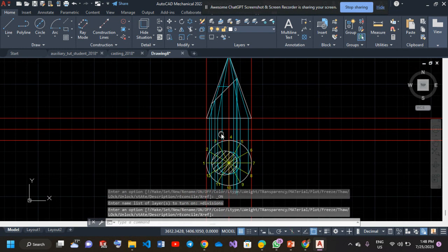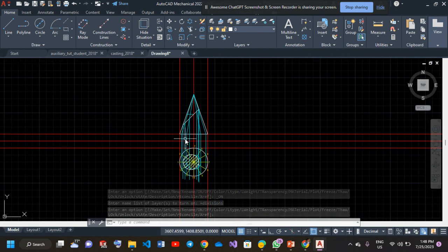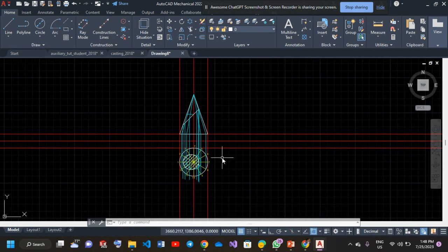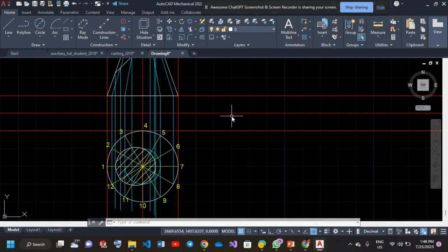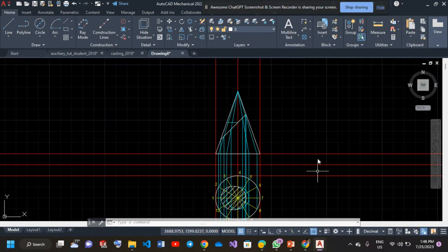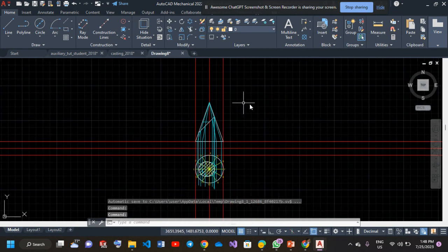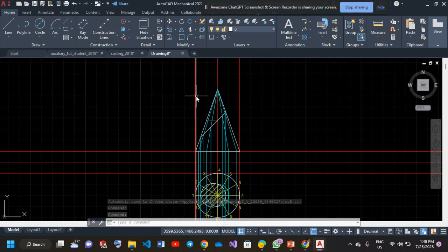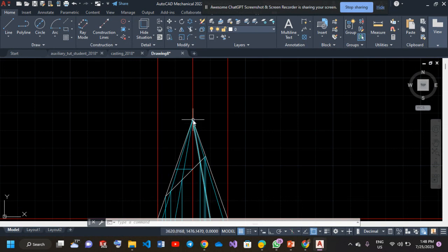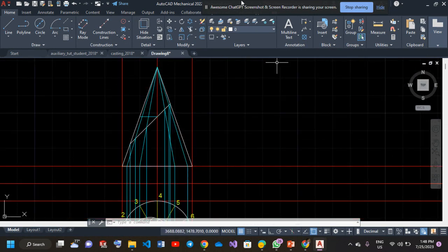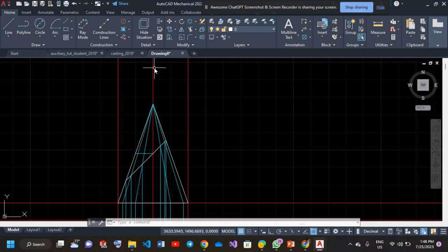Okay. So the next thing I'm going to do is to get the development of the cone itself. And to do the development, I need to get the development angle, which is theta, which we know is R on L times 360 degrees. So once you compute those figures, you get an angle of 120. To help me get that, I'm going to draw the development as a continuation from here upwards. And the angle is 120.